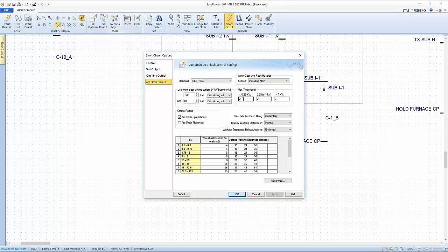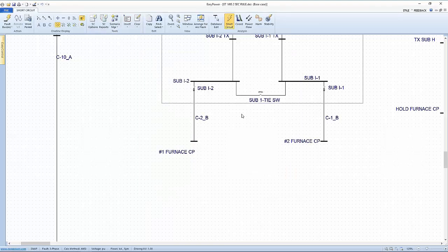Now, I'm going to discount 250 volts or less just because that's a different situation. But if we're getting incident energies that are higher, or they're limited by the 2-second rule at 250 volts or 1,000 volts, I frankly would be very concerned about the safety of the system. So let me jump into this and see if I can show you a couple examples.